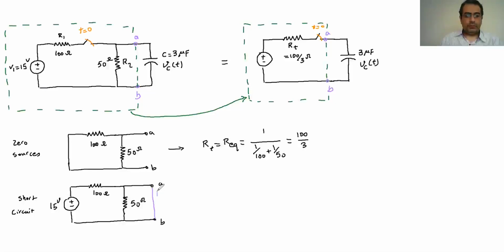and then we short circuit them. Whatever current goes through that is the ISC. If you look at this circuit right now, you can see that because we short circuit this resistance, all the current goes through, and there's no current through this leg here. So the I here is going to be 0. Nothing goes there because we short circuited; all the current just bypasses that. So it becomes a very simple circuit: one source, one resistance, and the current goes through that resistance, through A, B, and goes back. Nothing goes through that. Because of that, we can calculate the ISC very simply; it's just Ohm's law.